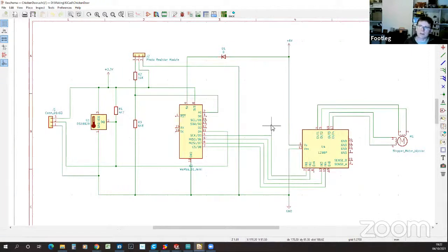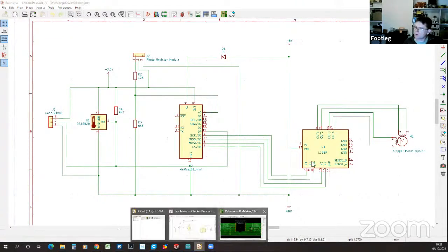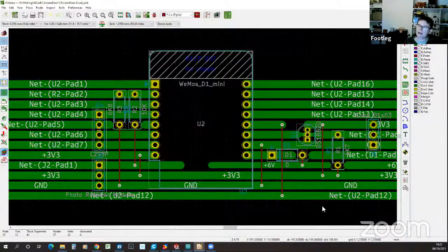I wanted to make this simple. It was only going to be a one-off, so I didn't want to build a PCB. So I instead went for strip board, and I used KiCad to actually lay out the strip board, and it proved to be a really nice technique. So I basically drew the green tracks as the equivalent of the copper on the strip board, and then my wire links are the red, where I use the top layer in KiCad and the components, and it's a little bit of fiddling where a component actually bridges across, so the resistor actually goes 1 track further than its width.